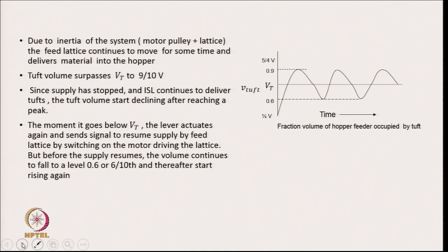By the time I press the switch, delivery is not stopped immediately, because there was some inertia of the feed lattice which was moving earlier. So, it will still continue to deliver some material within the hopper feeder. So, this is what is now on the right hand side, you see a diagram. This diagram is showing how the volume of the hopper feeder, the fractional volume occupied by the tufts within the hopper feeder is changing with time.